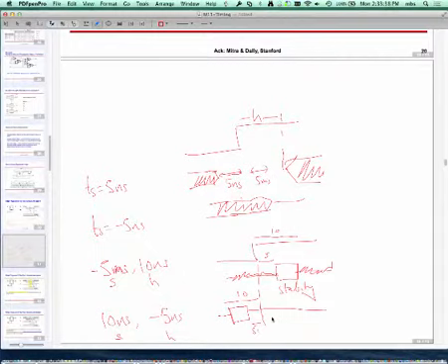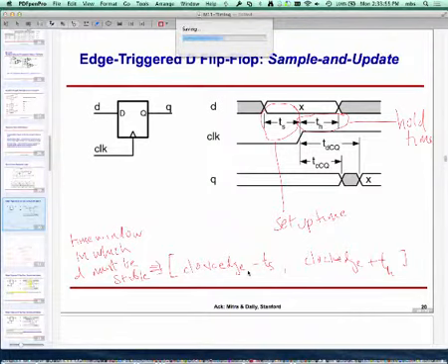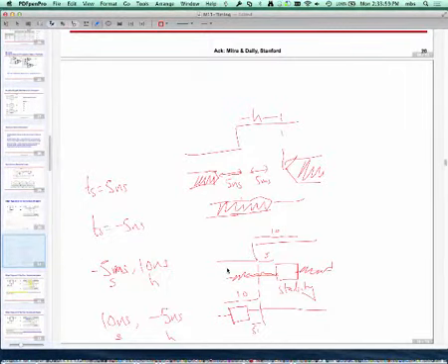And again, the condition which has to be met is that clock edge plus TH must be greater than clock edge minus TS, which is another way of saying TH should be greater than minus TS. So another way of saying it is the sum of the two must be positive. Okay, otherwise it's an infeasible flip-flop. So in the homework, as you encounter those negative values of TS and TH, keep that in mind. And what the homework problem asks you is, it gives you some data inputs and it asks you which flip-flop will you pick. There are 3 flip-flops there, A, B, and C. If you pick a flip-flop, would its setup and hold time be negative? So that's basically all that problem is asking you to do.